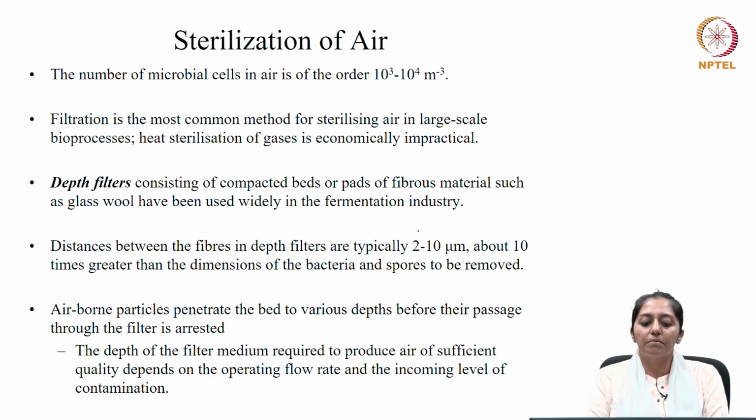Now, the distances between the fibers in depth filters are typically in the range of 2 to 10 microns and about 10 times greater than the dimensions of the bacteria or the spores which are required to be removed. So, it is very interesting to note that this kind of a setup is used to get rid of much smaller size bacteria present in the air.